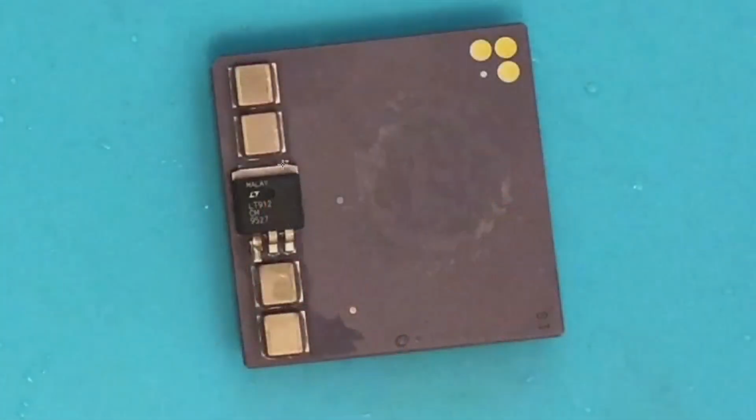Now another way to handle this dropout issue is maybe by replacing this chip here with something more modern, like a low drop voltage regulator. But nearly all of these have a different pinout here and are also very expensive and usually out of stock. In the end we need something that can easily handle even peaks up to 5 amps. Then the ones that have the similar pinout in the end can only give you marginal improvements.